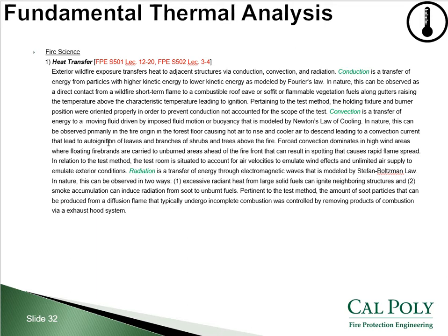Forced convection dominates in high wind areas where floating firebrands are carried out to unburned areas ahead of the fire front that can result in spotting that causes rapid flame spread, as was shown in the video. In relation to the test method, the test room is situated to account for air velocities to emulate wind effects and unlimited air supply to emulate exterior conditions.